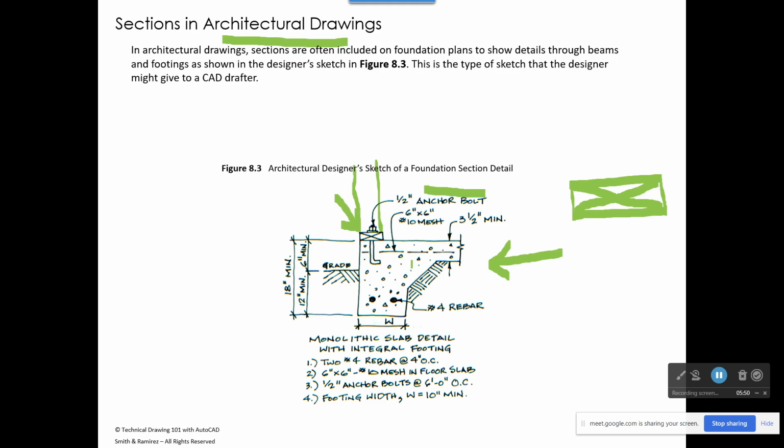And then inside here, we can see a hatch pattern, which is actually for concrete. It has some dots like this, and then some things that would represent maybe some rock or some aggregate. So this is a hatch pattern. It's called Conc, C-O-N-C, for architectural concrete. If you take the architecture classes next semester, you may get into using some of that.